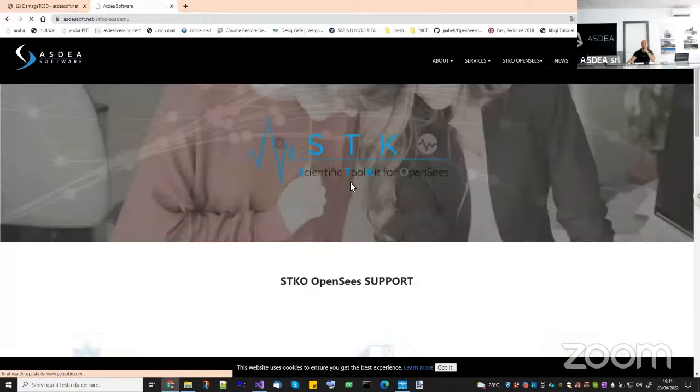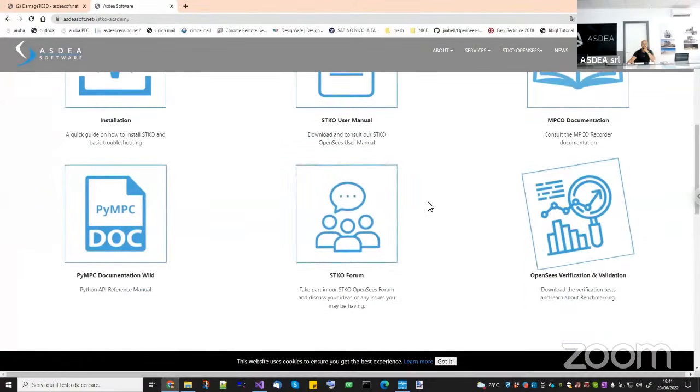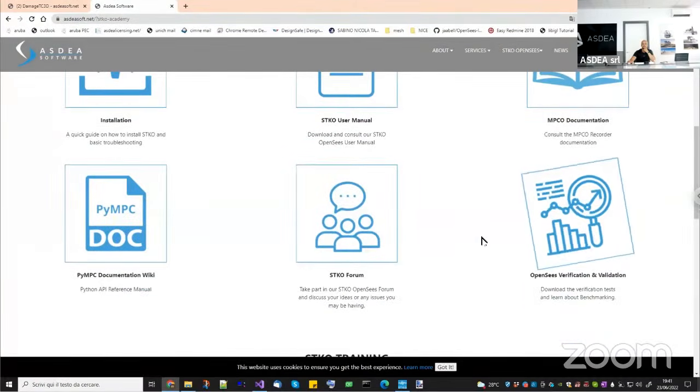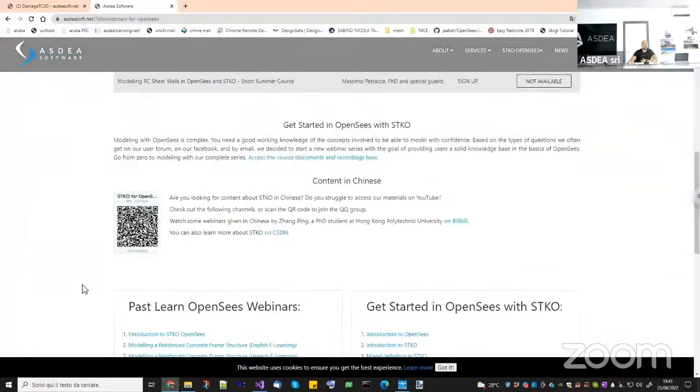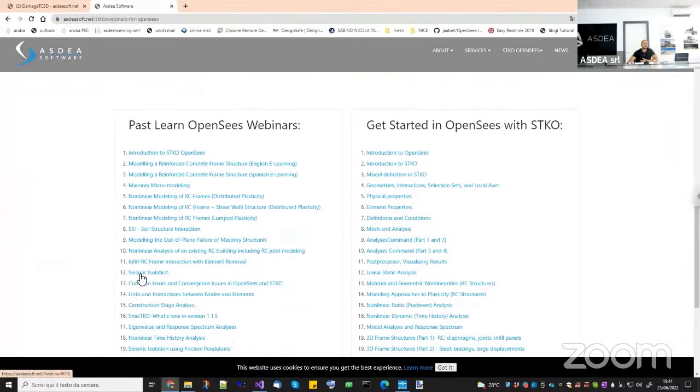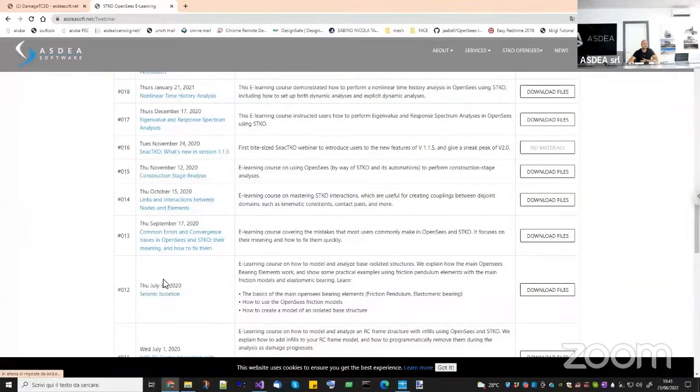You go here, STKO Academy, then e-learning courses, and then you have the course on nonlinear time history analysis. In this webinar I explain how to perform nonlinear time history analysis in both implicit dynamics and explicit dynamics, which is this one. And in the explicit dynamics I was simulating the blast, an explosion of a masonry wall. In the masonry wall, I was deleting pieces of elements according to a stretch factor.